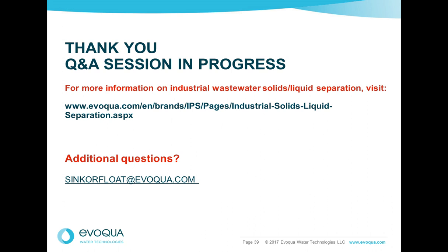As far as segregation of streams after clarifier DAF, again, most of this speaks to the holistic design of wastewater plants, and will often be required to either segregate or recycle flows back into the process if for whatever reason the effluent quality isn't met on a short-term basis. I hope that's answered the question.